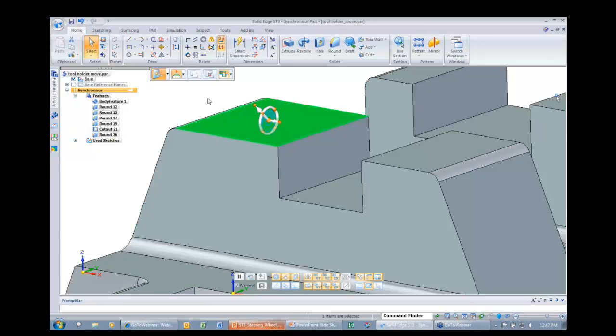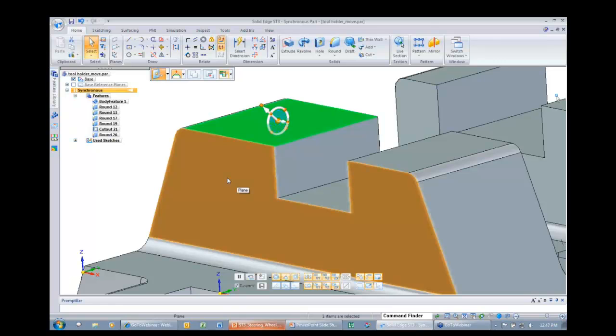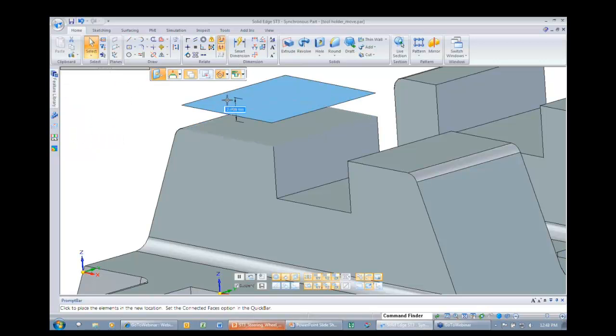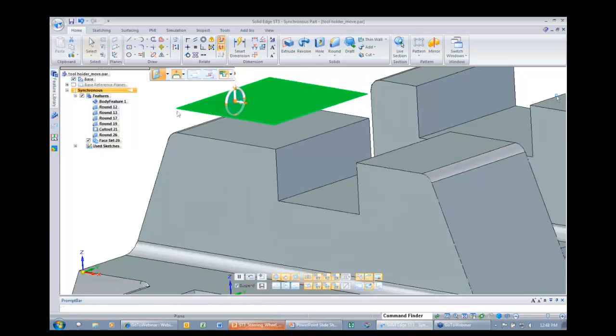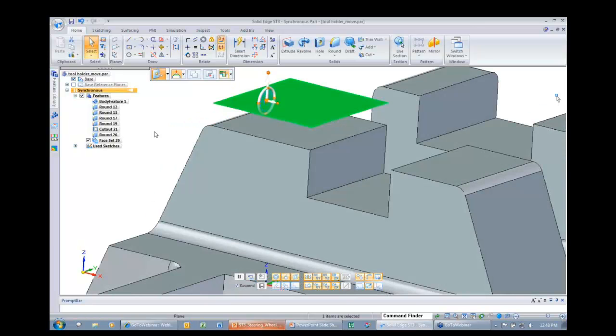Now you see that instead of it being straight up and down, I've now rotated my primary axis 45 degrees in that direction. By holding Control on all those, that makes a copy. Just to show you one quick example here, if I hold down Control and left click on the primary axis, whatever move, if I hold down Control, that's going to create a copy. So you see I've just created a copy of that one piece of select set, which is just that face. So that's why I don't have anything else there.